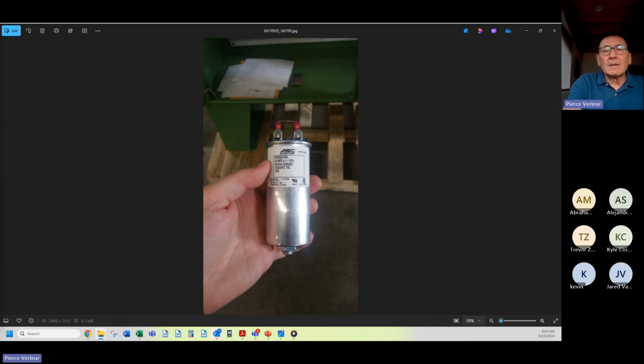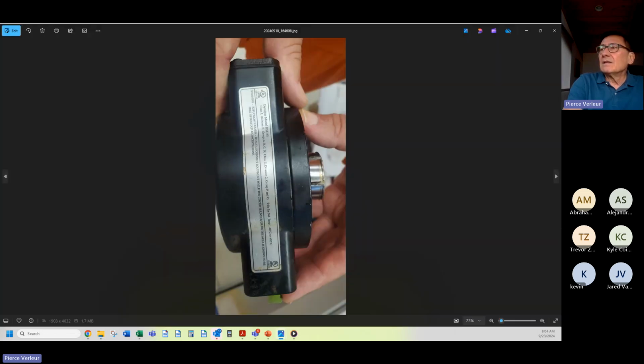By the way, as a final denouement, there's the encoders that we use. These are nice encoders, by the way, these Dynapar HS35 encoders. It's a 1-inch shaft on the tail end of the winch motor. It tells you how big the winch motor is because that's just the stub shaft for the encoder. These are standard quadrature line driver, 12-volt signals carried over 600 meters by a fiber optic link. I'm still amazed about that. I've been in this business a long time. It just goes to show you, you learn something every day.